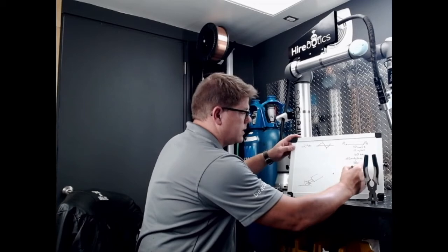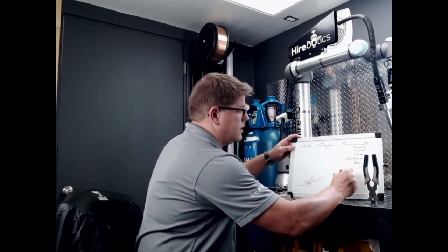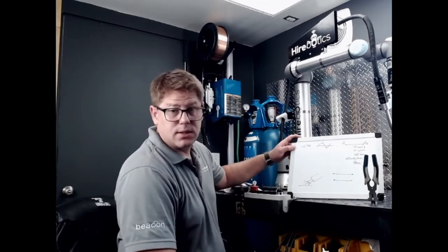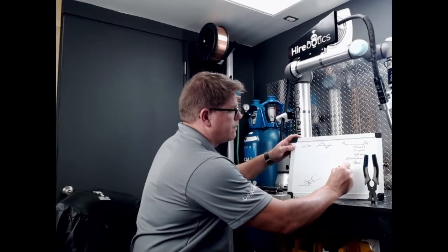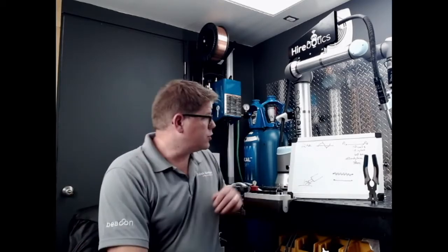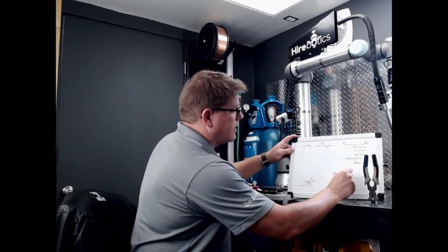It means, based upon your travel speed, the exact same weld, exactly the same distance, pretend those 2 lines are the same distance. If you're at 10 inches a minute, you're going to get 120 back and forth over that distance. If you change nothing, you don't change your frequency, you don't change anything, all you do is change your travel speed, and you double it from 10 inches a minute to 20 inches a minute, you're going to get half the number of back and forths over that distance.